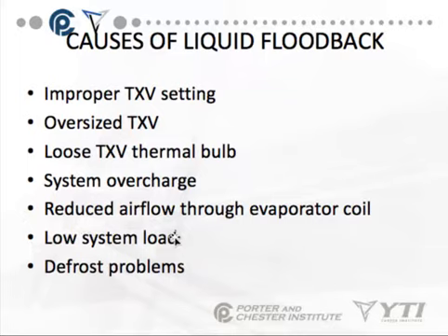We might also have a low system load, or defrost problems. Too much ice on the evaporator, which is preventing the liquid refrigerant from boiling off.